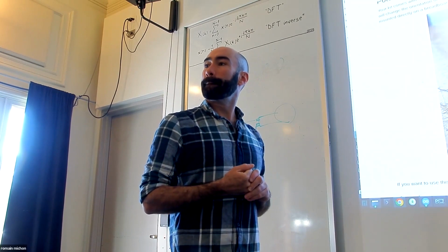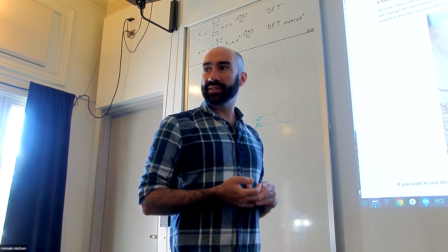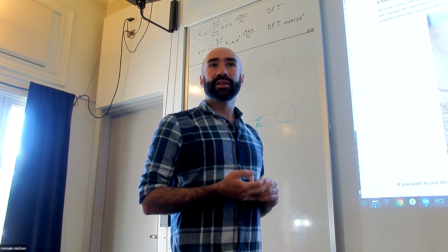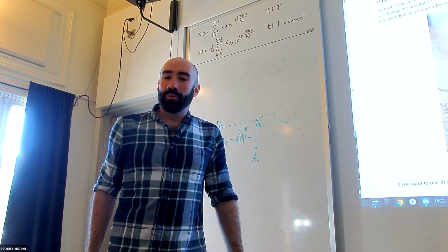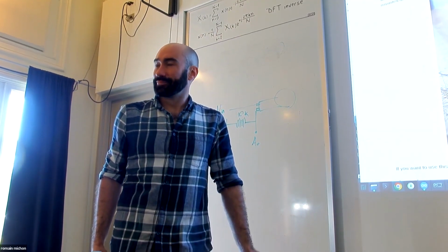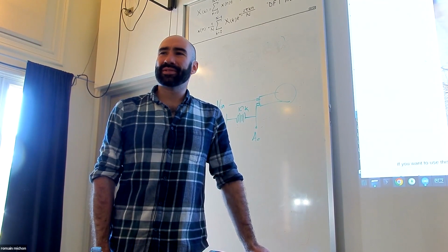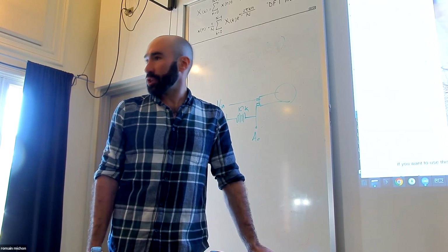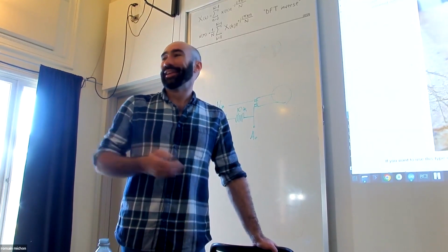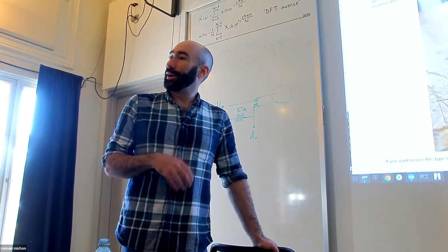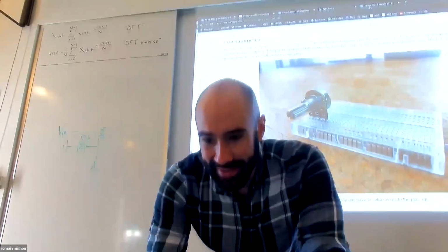Yeah? Does the Teensy 4.0 have internal pull-down resistors at pins? Yeah, some of them, not all of them. Can you declare them from the pin mode? Yeah, so the thing is, if I were you, I would not trust them. I don't really trust internal pull-down resistors in general. You can try, and in some cases it might work, but just to be safe, if I were you, I would just use good old resistors. Sounds good. Thanks. But that's a good question.